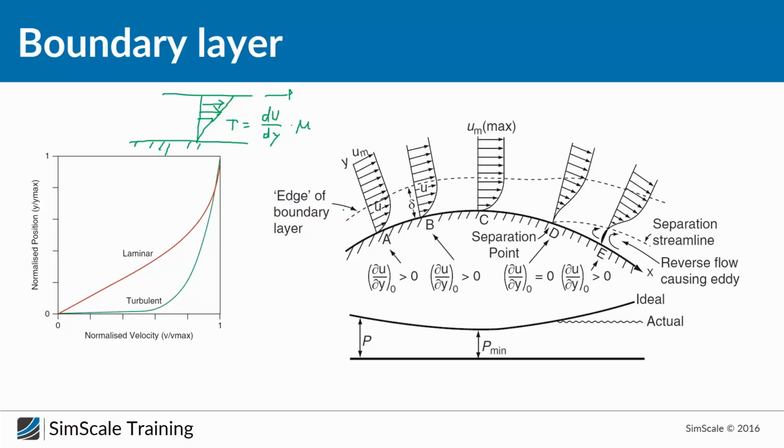It was also introduced by Prandtl, and a criterion which is widely used is the 99% criterion, which says everywhere where the flow velocity is under 99% of the free stream velocity, it's a boundary layer. And at the surface we have no-slip conditions, so the velocity is 0 as you can see in this image, and then the velocity is growing to the free stream velocity.